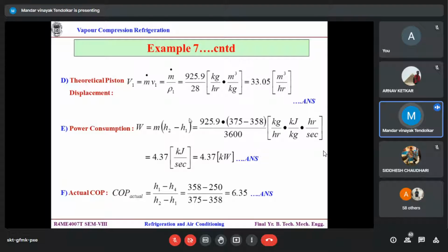Condenser pressure, evaporator pressure, 3 batches. So try to plot it now. Plot this on the R12 chart. You know the pressures directly, and we will try to find out the COP. Experimental COP already calculated, correct? Yesterday. The theoretical COP we will try to find out.